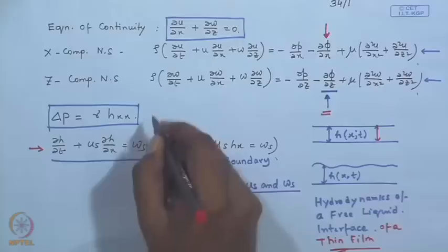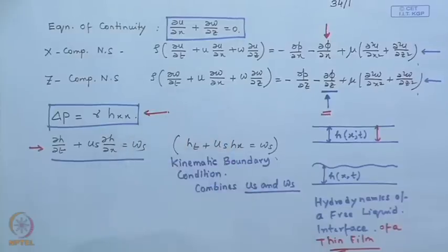We assume that the undulations at the surface are axis symmetric. Then we invoked the condition for what is known as the long wave instability, which essentially implies that del h del x is very, very small, close to 0. Once you plug that into the Young Laplace equation for an axis symmetric surface, this is the form you are left with.